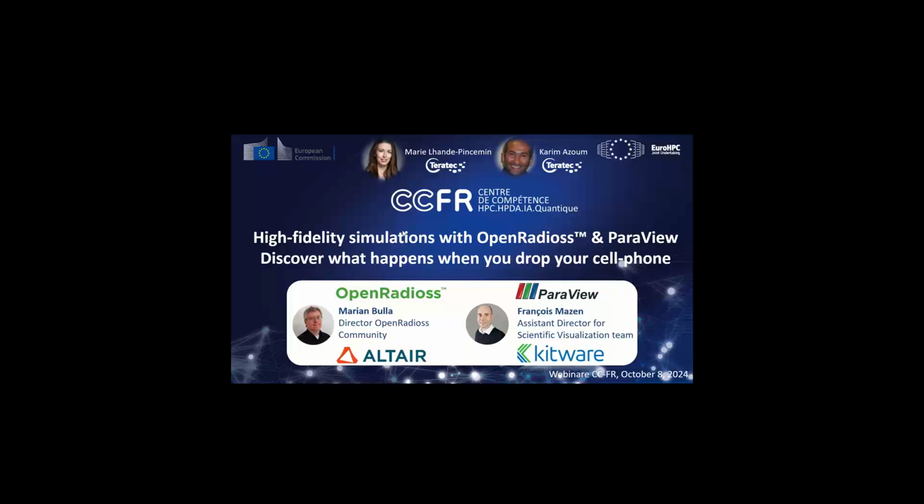For instance, in your workflow, you are always opening 4 views with this kind of filters, surface extraction, and so on. You can create once, record a macro of what you did, and then every time you reopen the data, you just have to click one button, and everything will be created automatically for you. Yes, so this is very flexible, the interface. You can also create some toolbars with the frequent filters you always use.